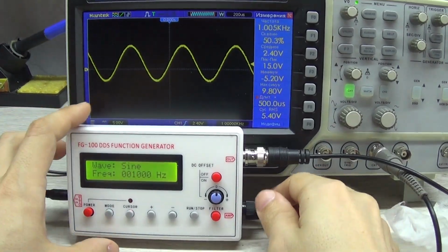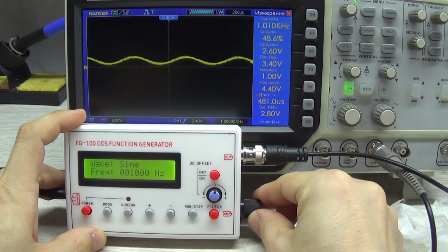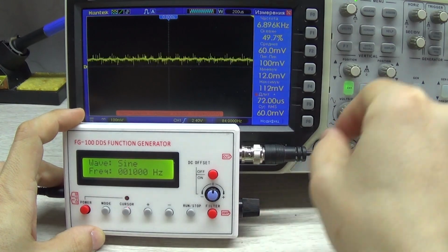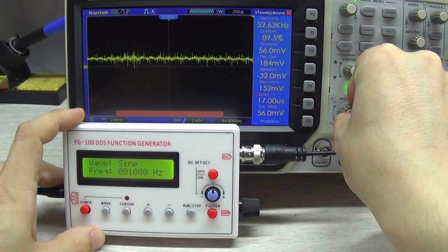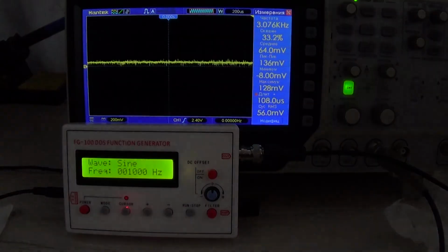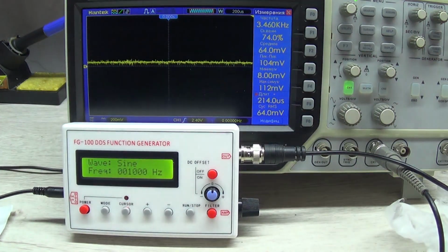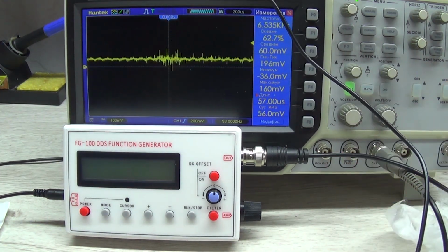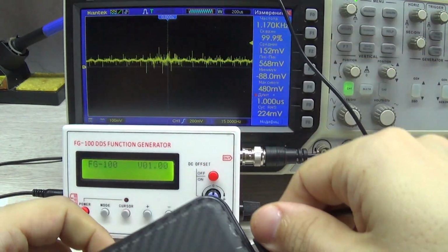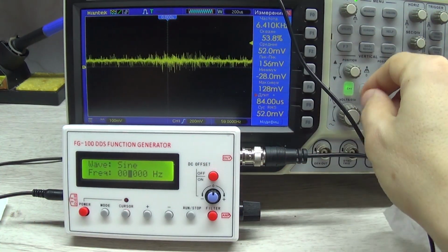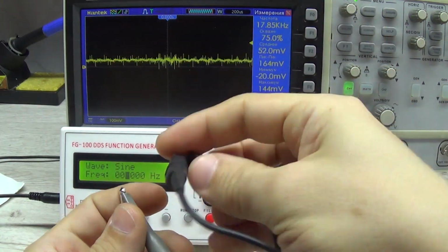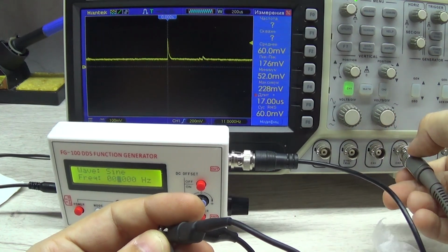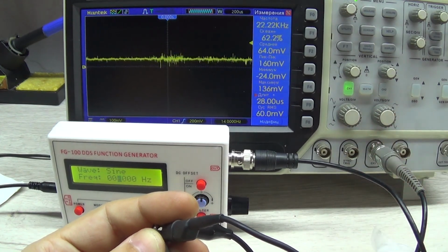Let's start with a 1 kHz sinusoid and see what minimum and maximum voltages our generator produces. At the very minimum, there is more noise than useful signal. It is not the generator itself that is noisy, but various sources of noise near my workplace. I disconnected the power supply and nothing has changed in terms of noise. Let's try to connect the power back in. No miracle. What is it that's picking up noise? It's the oscilloscope probe itself that's picking up the noise. Yeah, I also turned off the workstation lights.